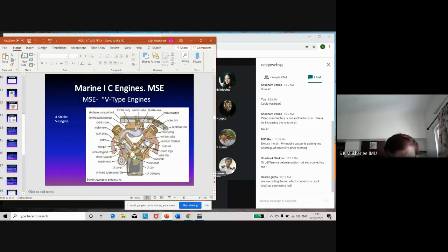So here is the V-type engine, and the two sections that are shown are one through the inlet valve and one through the exhaust valve. So there are two different sections which are being shown to you. If you see, the inlet valve has the air passage coming in from here. It comes from here, passes through the inlet valve and goes into the cylinder. And in this case, that is the exhaust valve. When the piston goes up, if this valve opens, it is discharged from here. Okay, so they are shown in two different sections. In this section, the exhaust valve has been cut through, and in this case, sorry, the inlet valve has been cut through.